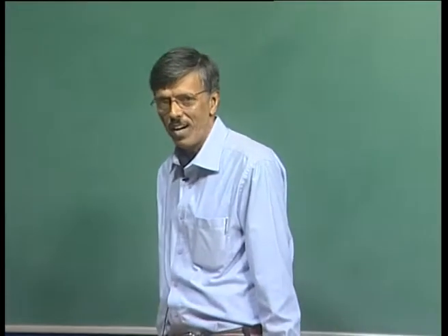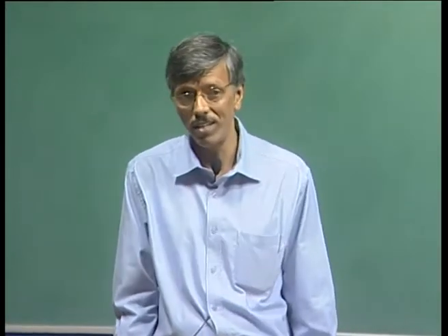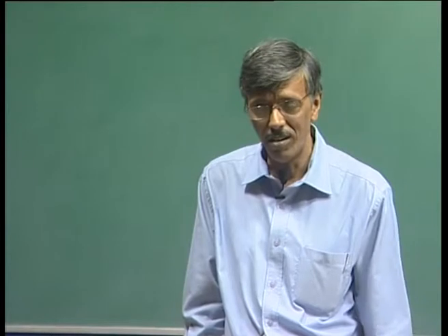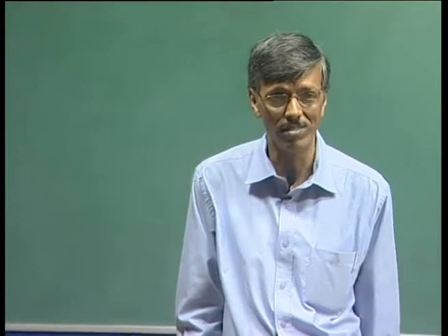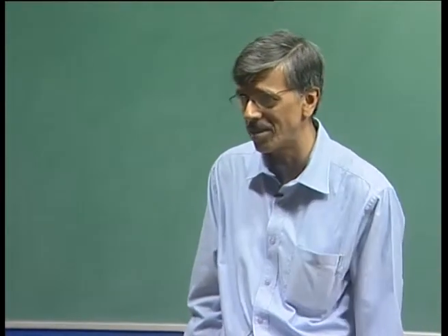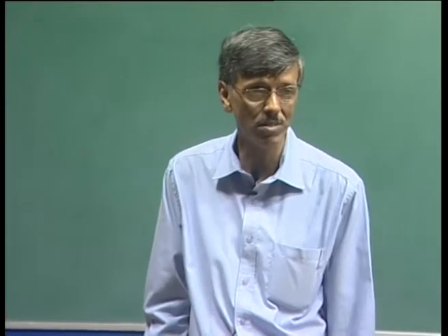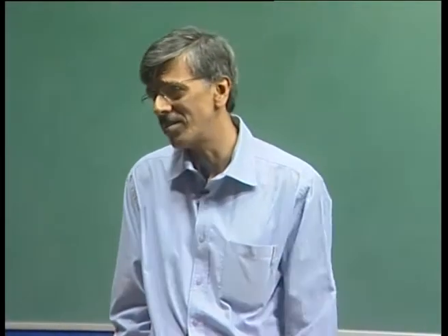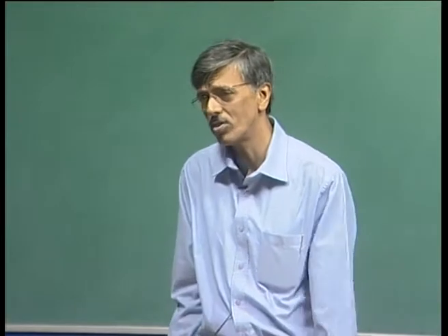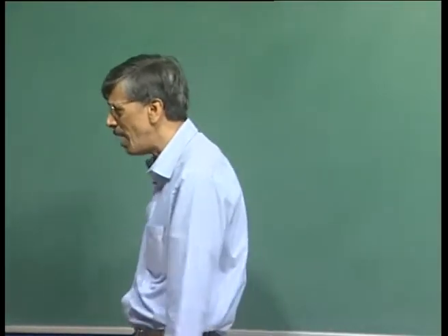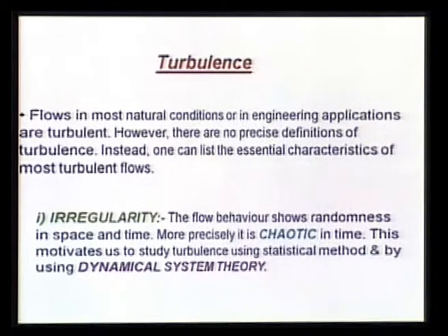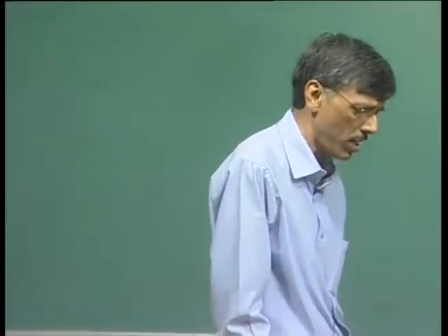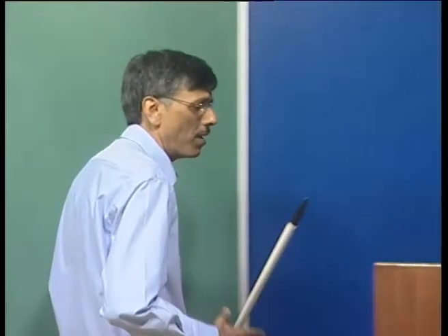deterministic structure. And you are now really ready to appreciate that point of view, because that is what we have done with our POD analysis, that we will take a completely stochastic dynamical system and project it onto a deterministic basis. So, those deterministic bases are nothing but your so-called coherent structures of turbulence. Okay. That is why people may like to study turbulence using statistical methods, or they may like to study it in a dynamical system framework like what we have just now done.